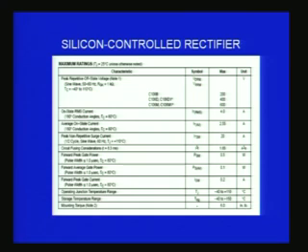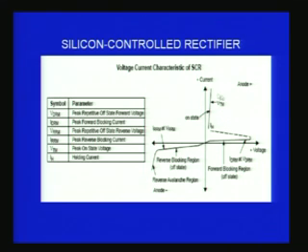The most important point in all devices is that one should learn from the data sheet. You must look at the data sheet, because the data sheet is the data given by the manufacturer. He gives you all the limits within which this device can be operated. Therefore one should carefully go through that, and you would find it is also 200, 400, 600 volts you can operate this device at in different variations, and the RMS current is about 4 amperes, etc. All the important details will be available here. One should go through and try to understand the characteristics of the device. They also give you the characteristics, how it will look. You can see it is exactly similar to the one I showed you. The characteristics are shown with the various regions of operation correctly demarcated.